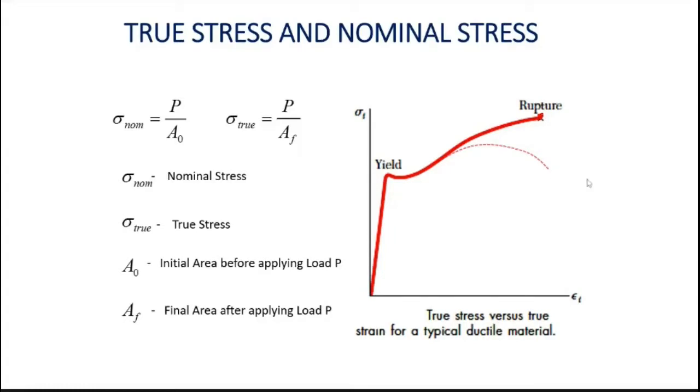So last class, someone asked why the load is reducing. When I apply maximum force, at the time of break, why is the load reduced instead of increasing? The answer is this. In the real one, your load is increased. It is not reduced like this, right? Because your area is reduced, right? Your final area is very, very much less.